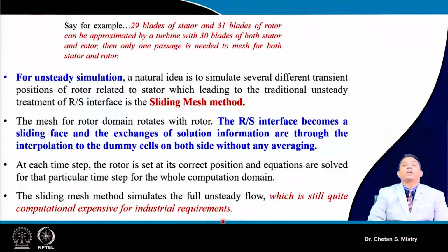For that only we can go with this kind of configuration, else it will be a very expensive affair. So mainly when we are doing our analysis at the initial stage or design stage, we go with, say, the mixing plane approach or frozen rotor approach, and based on that we finalize our design. Later on, in order to understand the detailed flow field, maybe we will go with unsteady simulations.